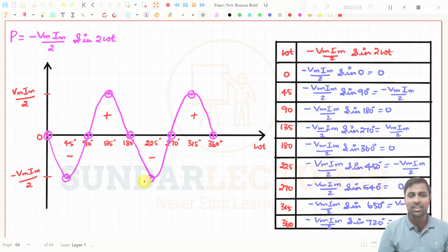Then what are these powers? I have already told you, if the power is delivered from the source to load, then load to source, then source to load, then this cycle will repeat throughout, which means these powers cannot be utilized by the load nor by the source. These powers are also called oscillating powers, and we are calling these powers reactive powers.